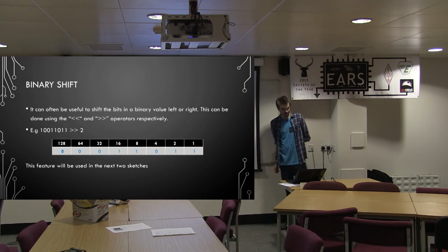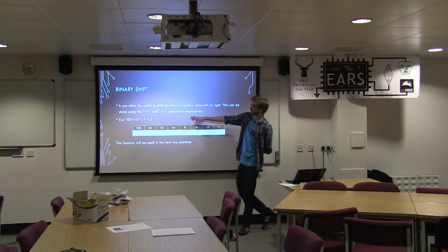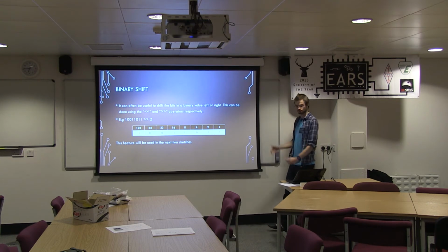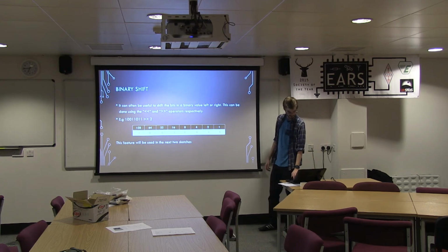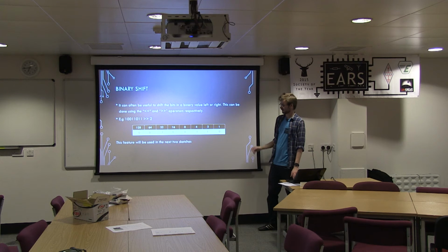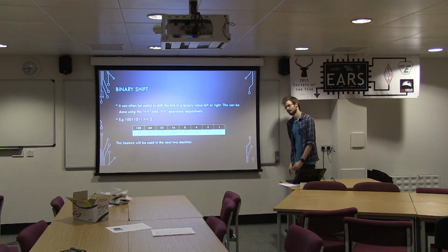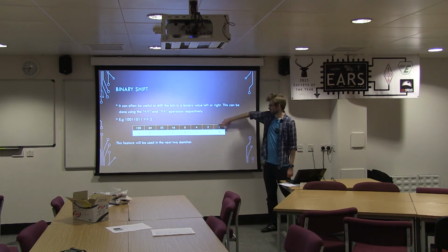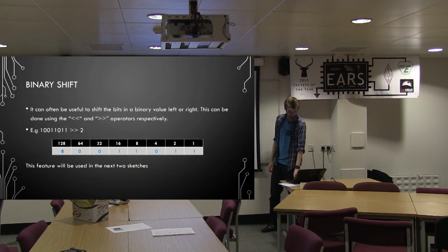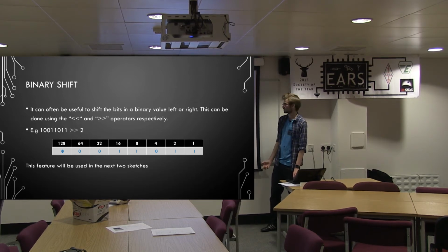So another useful thing is binary shifting, which are these operators here. The 2 arrows, they literally just take your binary number and they shift it to one side or the other. If this is nicely animated. So that is a binary right shift of 2. So it took the number and literally just moved them all to the right. That is the equivalent of dividing by 4. So effectively you're losing the bottom 2 bits of the resolution and moving it all up. This is useful for very specific things, talking to devices, and is what it actually implements if you're running a division on there.